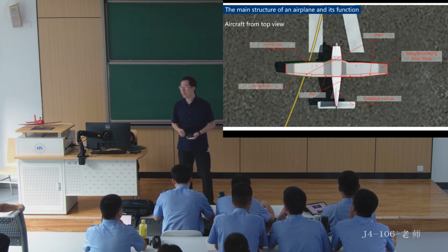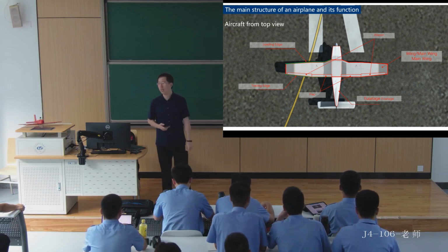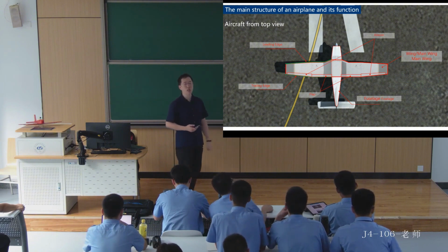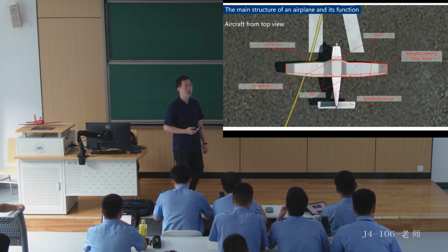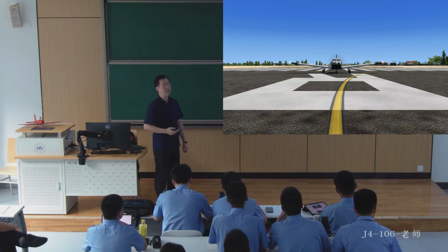So I hope that in the future, our students will develop a good habit before flying, right? We need to check whether our operating system is functioning normally, whether the control surfaces are responding correctly, and whether the direction is correct. All right, let's move on to the next step and look at the beauty of the aircraft from another angle.